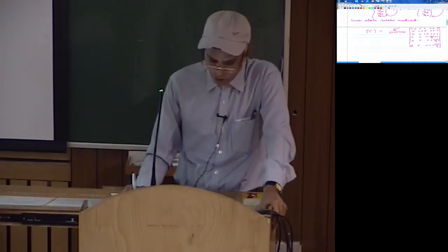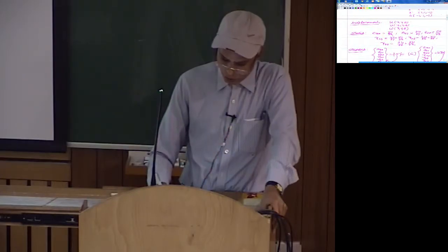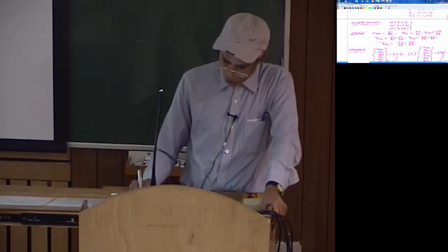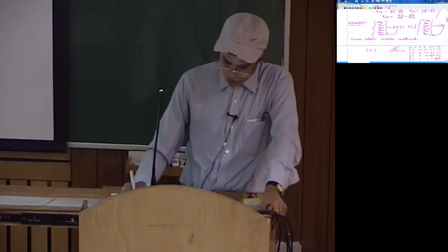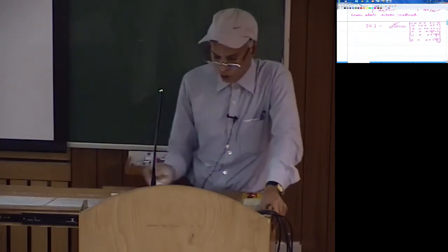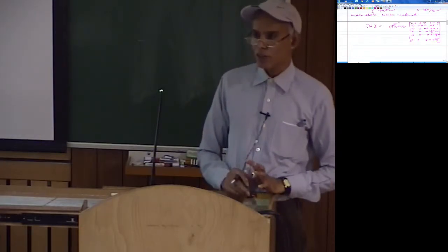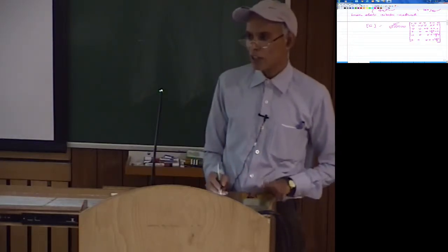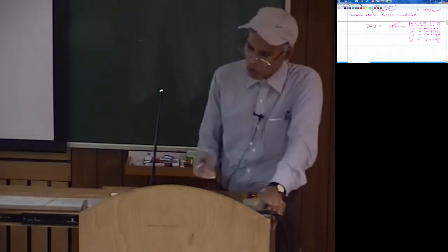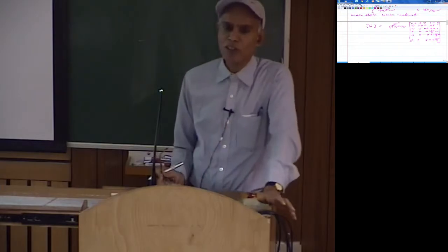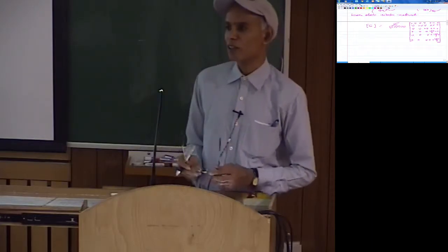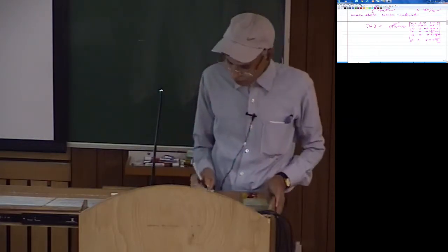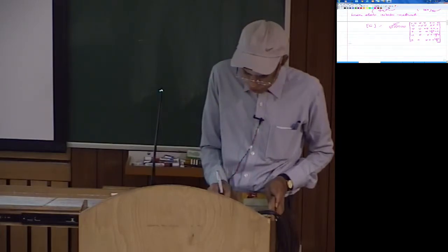So this is as far as your displacement. So this is now 3 variables here, 6 components of strains, corresponding 6 components of stresses, and then the constitutive relation. Now finally, to develop the element level governing equations, we need to write the expression for total potential energy. Of course, one can also come from the three stress equations of equilibrium, then write the weak form corresponding to those, and then from the weak form you can finally write either your integral functional or develop the element level governing equations. Here I am writing directly the total potential energy functional.